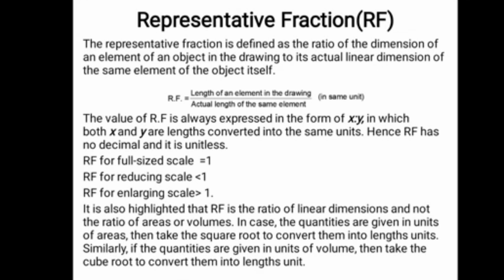Now, the representative fraction. As we have seen with enlarging or reducing scales, this representative fraction plays a very important role. By multiplying the representative fraction with the actual length, we can find out the length of the element in the drawing. We can reduce or enlarge by multiplying with this representative fraction, so this is a very important aspect. Using it we can enlarge, reduce, or draw with respect to the actual scale of the drawing.